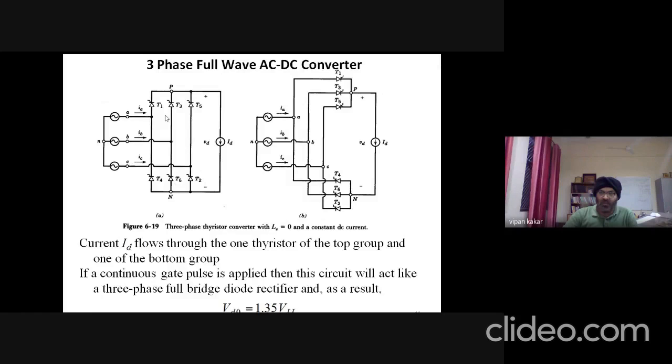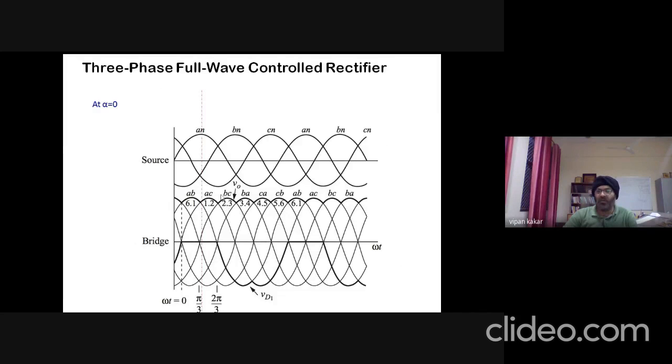Now again the same thing. Thyristor 3 is conducting now. So now this phase is positive, phase B. Current follows this path through T3, going through the load again from top to bottom, and pairing it with T2, it will go through the neutral through phase C. So now the voltage at the load will be across phases B and C. So VBC will be the voltage at the load due to the conduction of thyristor 2 and thyristor 3. And then the cycle continues.